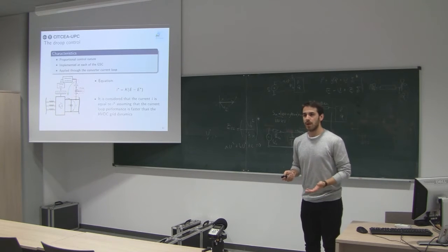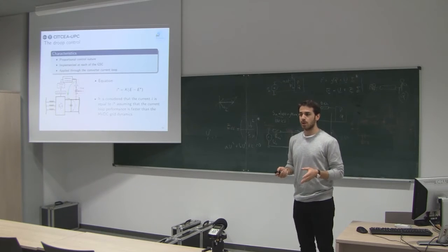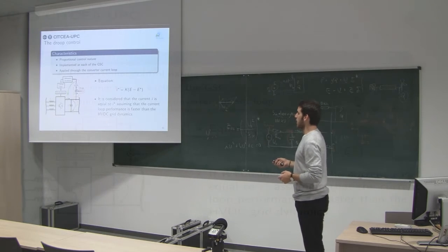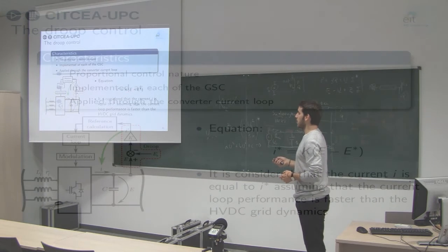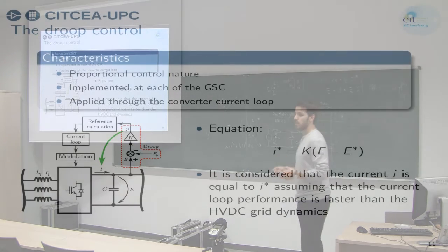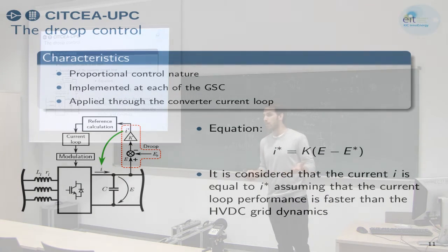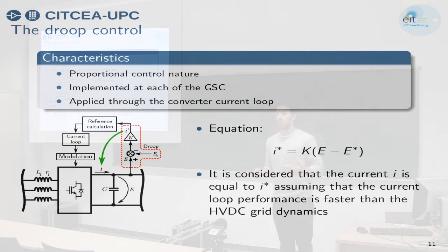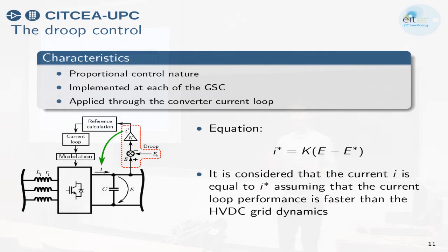It's even simpler than a PI controller. It's a proportional controller. So here you can see that it is like this. You have the voltage measured at the terminals, then you have a reference voltage, which is typically the rated or nominal value of the system. So imagine that you have a plus minus 300 kV system, so you have 640 kV there to regulate. So this should be the reference value, okay? It is the rated value of the system, more or less, okay?